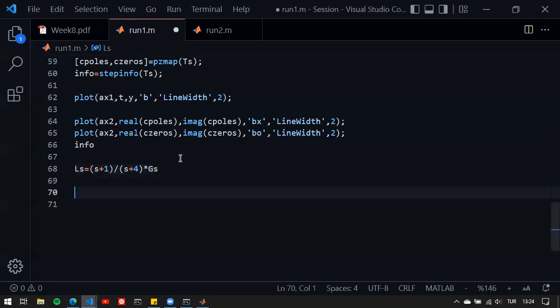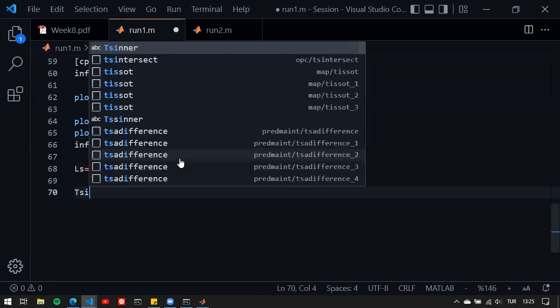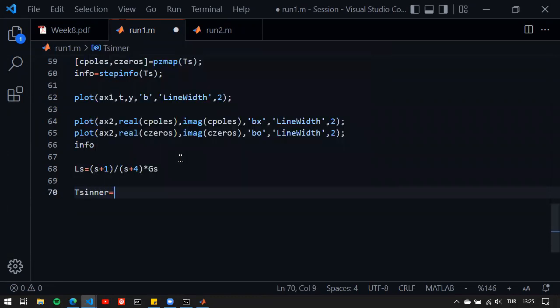In this case, using a PD controller in the feedback gives us an inner loop transfer function, which is basically updating the root locus again, but using a feedback loop. And then we're using this as the open loop in order to design a PI controller. So there's a two-step root locus manipulation here. First, using the PD controller, we get a certain inner transfer function. And then we, again, add a pole at the origin, try to add a 0 out of the dominant region, and then choose a P-type controller, basically.